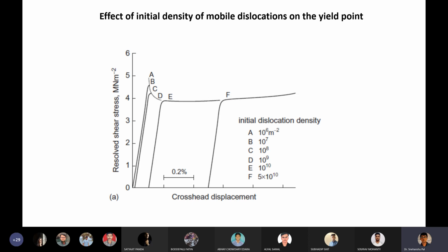All kinds of discontinuous slip are really not much with respect to resolved shear stress, because the resolved shear stress also decreases as the Schmid factor slowly deviates from its maximum value. That is the argument, but this argument is still not so strong.